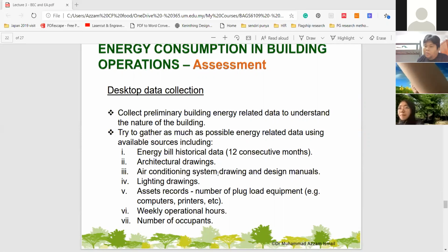Just now we can clamp onto the air conditioning to find out the amount of electricity it uses, but for artificial lights it's not easy because there are hundreds of them within one building. You can't clamp onto every one, so you probably clamp onto one, measure it for a certain amount of time and multiply. To multiply, you need to know the numbers, of course.